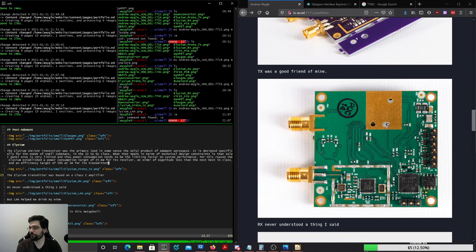What really made me weep was discovering just how bad the error rates are and how much the ECC is relied upon for normal operation on Seagate Constellation drives. Yeah, anything that's QLC, a lot of the time you can look at what the actual write endurance of this thing is, and it's like 500 writes. It's like, oh boy.